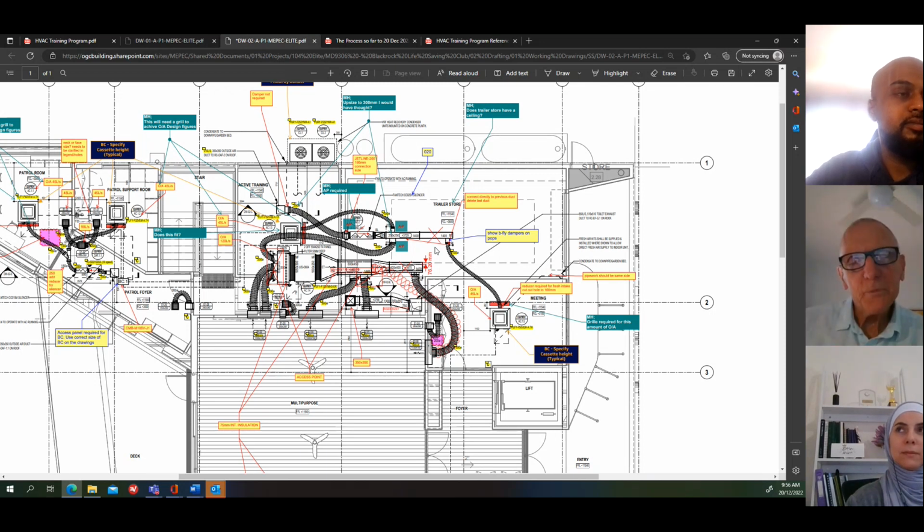So just be aware of that, because when we talk about value engineering, it's these little things that can make a difference. Now, on a big project, if you can delete, say, 100 pieces of that last piece of duct, if you don't need it, you save 100 times, let's say $500. How much is that? $50,000?